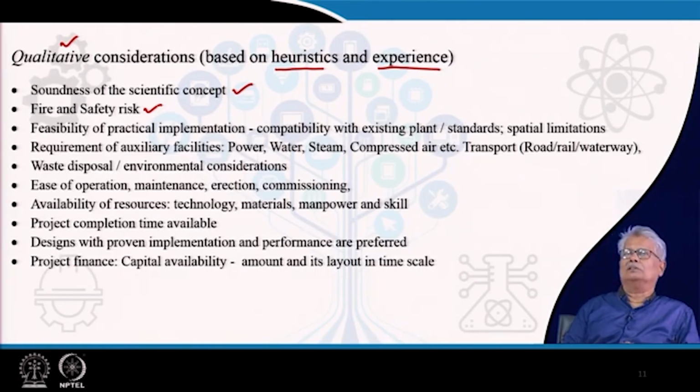A very common practical limitation while designing a physical plant is the spatial limitation. Really, if we think of having an exchanger with 6-meter long tubes, whether we really do have that space or we do not have that space is a question that needs to be known to the designer first. That means the feasibility and the practical implementation is the first and the foremost thing that has to be ensured if a design has to work.